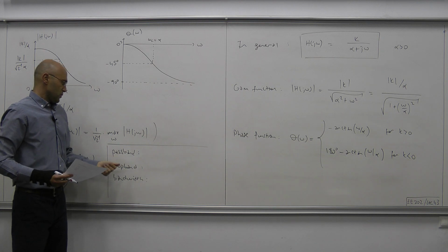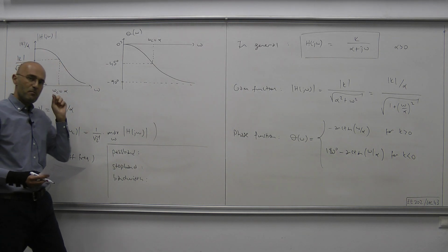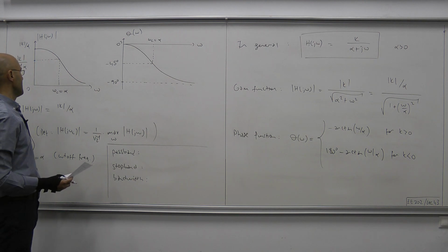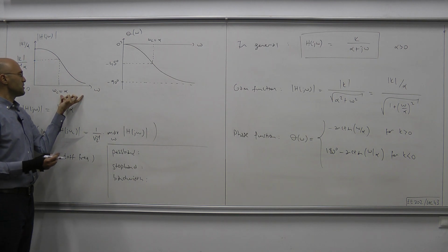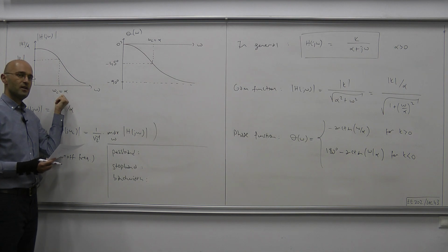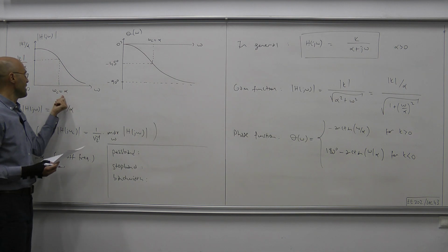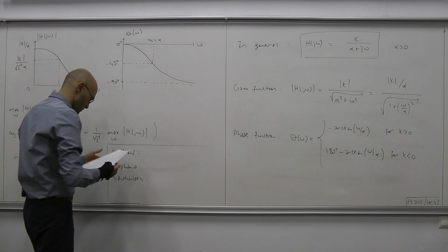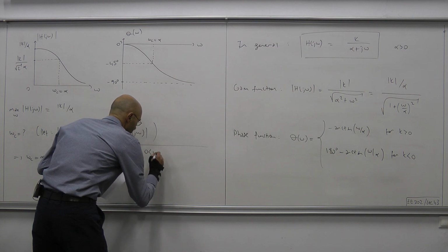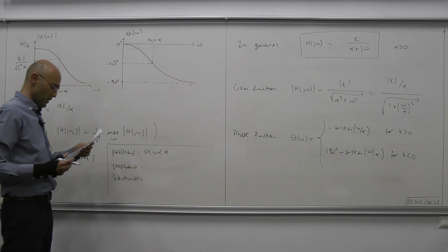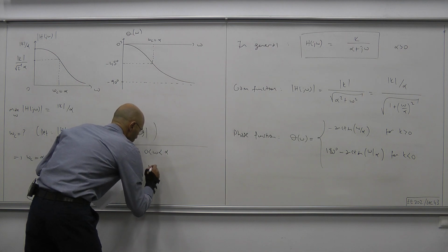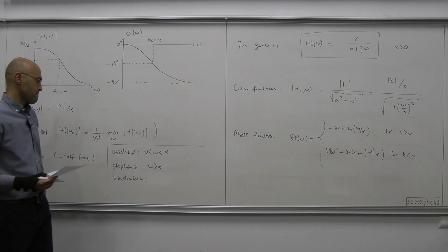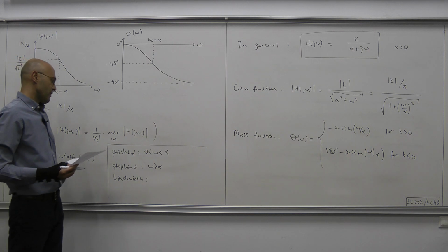Okay. So the cutoff frequency marks the border frequency between passband and stop band. Therefore, this part is the stop band. That is, the frequency is larger than cutoff frequency, or larger than alpha. And this here, from 0 to alpha, is our passband. Okay. So omega less than alpha is our passband, and all the other frequencies, namely omega larger than alpha, those frequencies make our stop band.